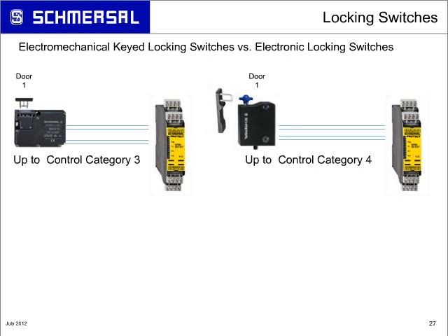The mechanical actuator, that key that gets inserted, you can still have the possibility of mechanical failures if it's not installed and designed properly. In doing that, you can only achieve a control category 3. To be able to use an electromechanical switch in a control category 4, you typically need a separate safety switch to be able to determine key breakage of that system as well.